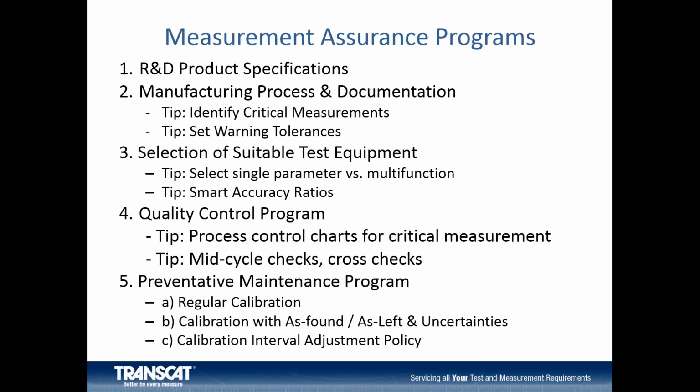Okay. So, measurement assurance programs. If you design your measurement assurance program, you can help limit all the time you spend on these things. The measurement assurance program is more than a calibration program. It's a thought process. It links the related measurements through the entire product life cycle, from concept to end product. Hopefully this approach and these guidelines will ease the burden of solving one of the most dreaded situations in the measurement world, the evaluation of out-of-tolerance instruments.